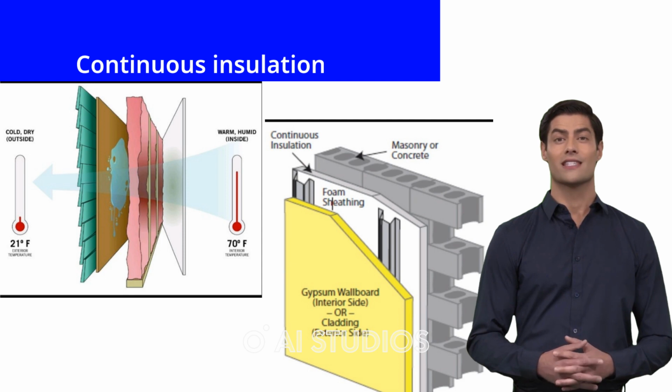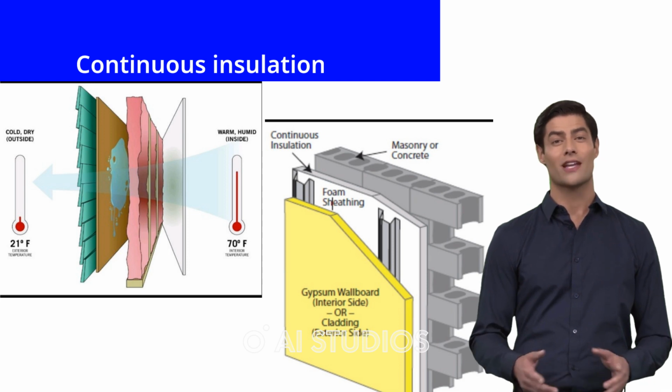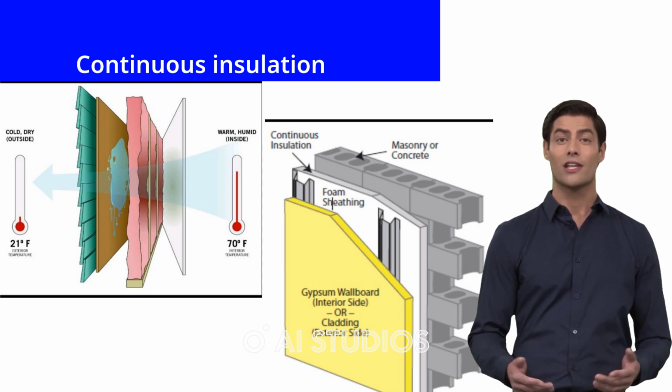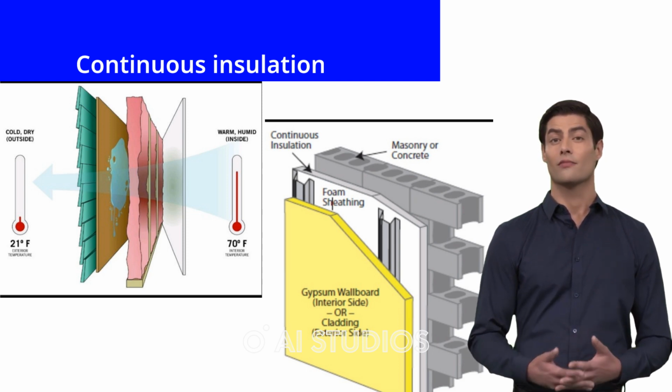Insulation that is continuous across the structural members without any thermal bridges other than windows and doors. The insulation design involves using high-performing insulation materials to cover the entire envelope to reduce heat transfer via walls, roofs and foundation, minimizing energy losses in the building, which ensures that the indoor temperature remains constant.